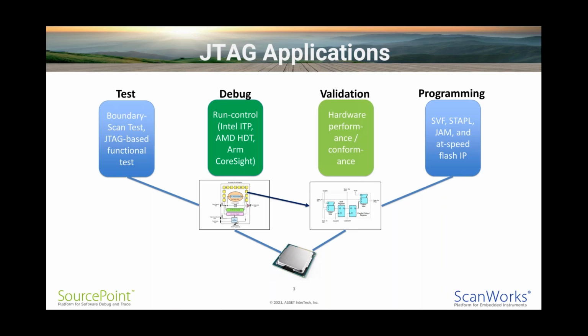Really just a collection of data registers and instruction registers, and around the perimeter of the device, behind each pin, there are boundary scan cells, with really only a handful or two of gates associated with each. The collection of which acts as a serial shift register around the perimeter of the device, and also parallel shifting between the outside world, the external pins of the device, and the internal system logic of the chip.